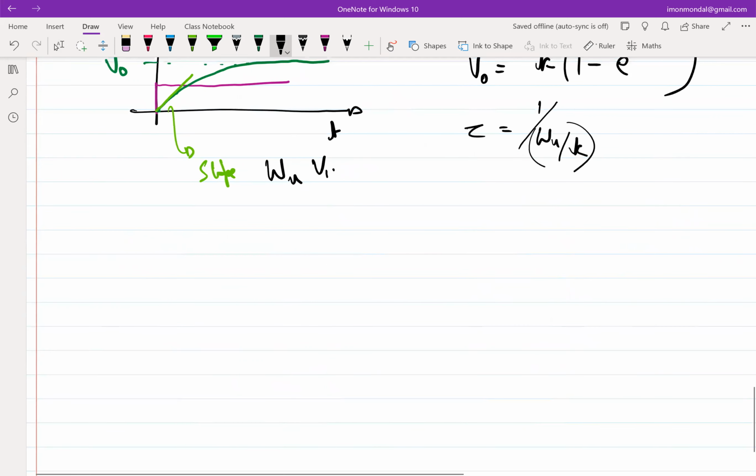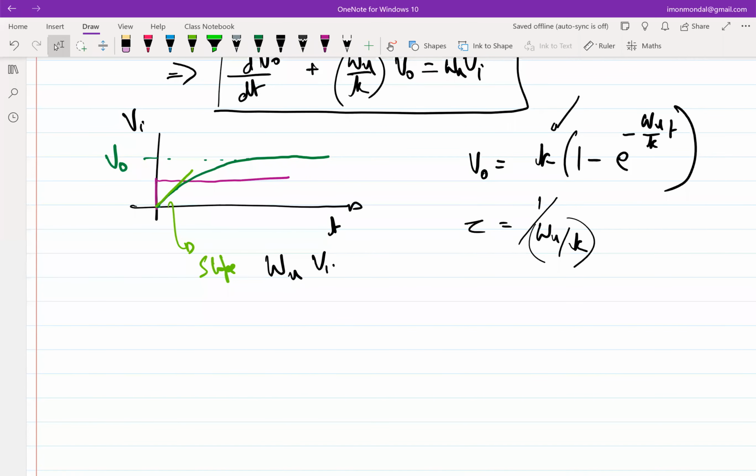Okay. So this is as far as the DC picture is concerned, but we not only want to amplify our DC, we would also like to see what happens if we put in a time varying signal, for example, a sinusoid. We already have a well-established method of figuring out how a system responds to a sinusoid: we first go into the Laplace domain, then replace S by j omega, and then we get the transfer function. That omega is nothing but the omega of the input sinusoid. So we will go in that route.